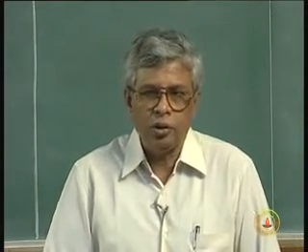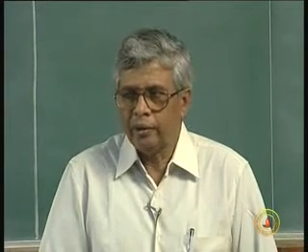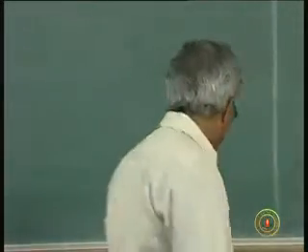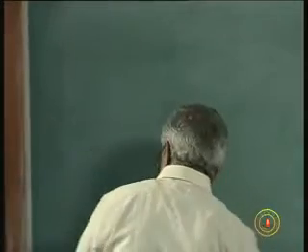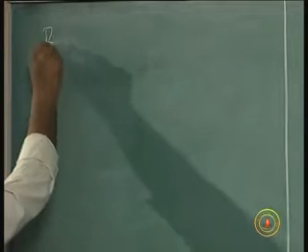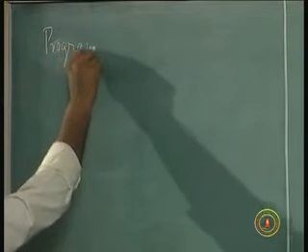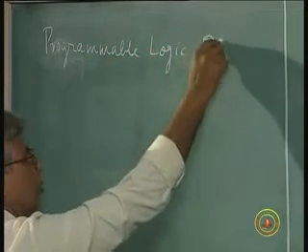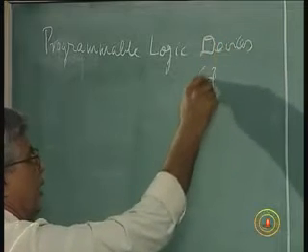In which case I don't have to go about and get another IC and do a different design, if I can make some changes in the design and use the same hardware. This concept is called programmability. Programmability is a very important concept in digital design. That is how we get microprocessors and computers. Today I'm going to talk about programmable logic devices, PLDs.